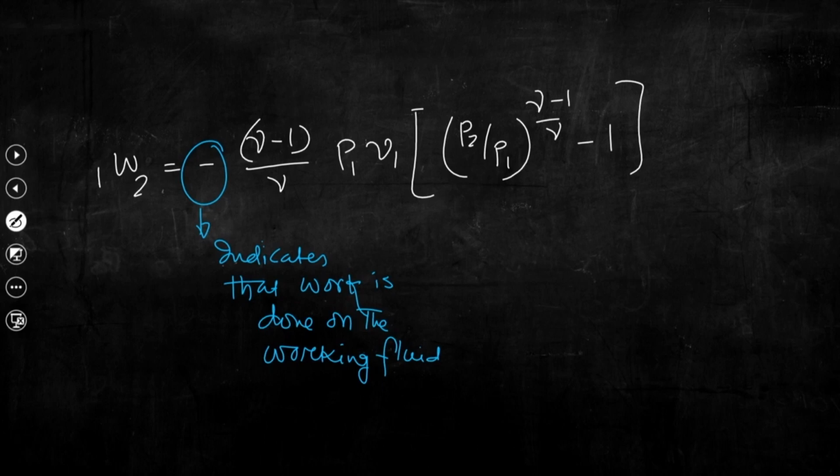So, basically these two are contradicting. If we need to get more pressure ratio, then certainly work input to the compressor will be more. If the pressure ratio is more, then energy input in the form of work that should be supplied to the compressor will be more, and then the net turbine work output will be less. But if we can increase the pressure ratio, then cycle efficiency will be maximum.